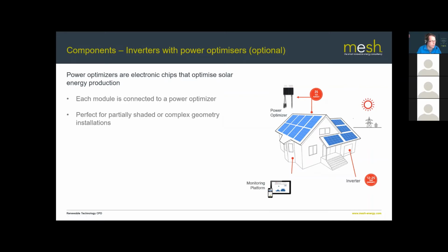So this roof here will have a different level of light from this roof here. And what you'll find is that when these panels are producing lots, these panels might be in the shade and vice versa. And that will mean that with an MPPT system, you'd never get the maximum output from the system.